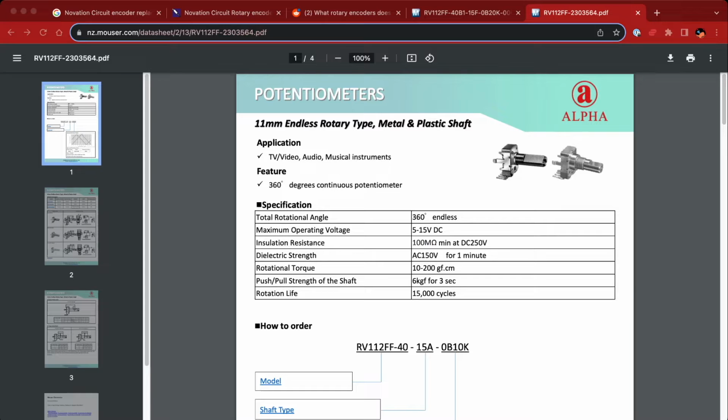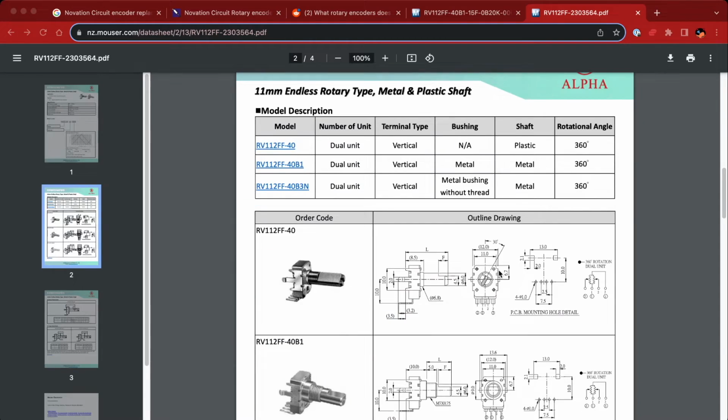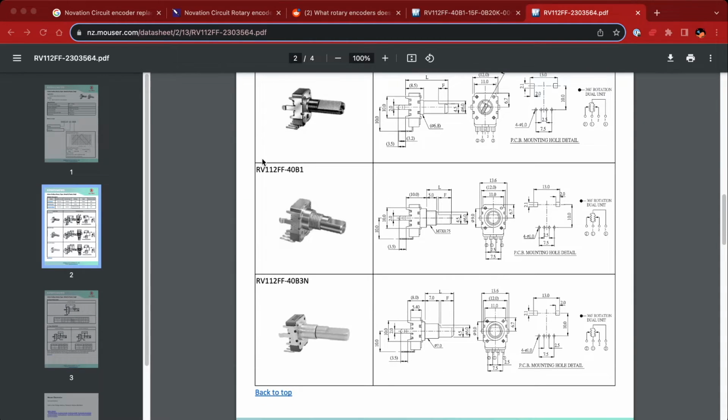Before we get started with that first example, though, I want to show you a few things right here in the datasheet. First thing I want to show you, these are obviously the physical dimensions of the part itself. But here's the curious thing. A normal potentiometer symbol just looks like a squiggly line with a line down the middle, and that represents the shaft. A normal potentiometer only has 3 pins. This one has 4. And the way that this is configured, that 4th pin is another wiper.